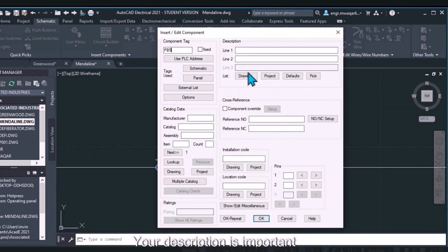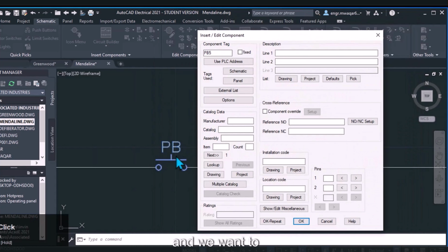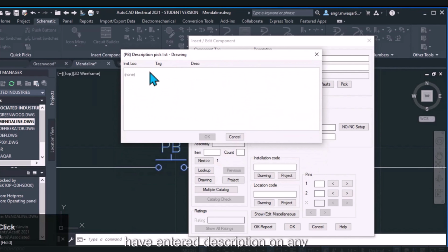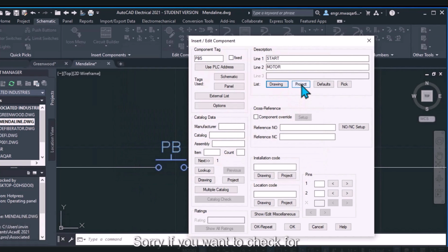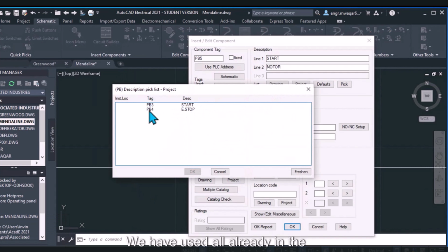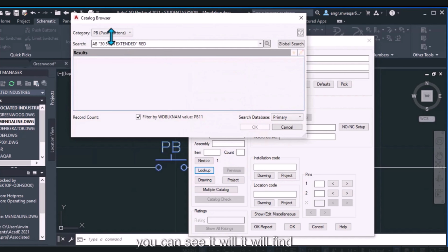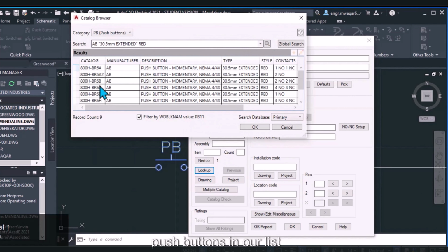So imagine you are the engineer on a massive factory floor project. Okay. You have used push buttons PB1 through PB4 on page 3. Two weeks later, you open up page 87 and drop down a completely new push button. You've totally forgotten what number you were on. Exactly. But the software instantly queries the background database, sees that PB4 was used 84 pages ago, and automatically names this new component PB5. That's so seamless. It continuously checks this project-wide registry so a component's identity is never accidentally stolen or duplicated.